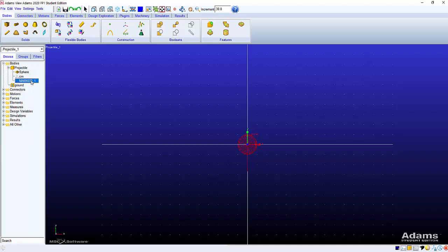What do we mean by marker? A marker is actually a coordinate system. We learned the coordinate system before; it consists of 3 perpendicular axes that can be defined by an origin and orientation. In general, for this sphere, this marker represents the center of our sphere, which right now will be located at the origin. The orientation of this marker, which is the rotation with respect to the global coordinate system, doesn't have to be reoriented because the sphere is actually symmetric around all the axes.